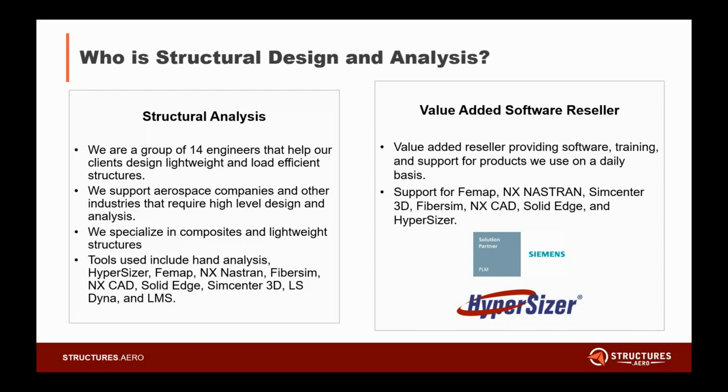Essentially, the more nodes, the higher order your elements, the more complex your interpolation functions get. And the mappings at that point become different. But it's the same general idea. You're taking this quadrilateral element and you're moving it to a nice square master element that facilitates the numerical integration of the computations that are being completed.